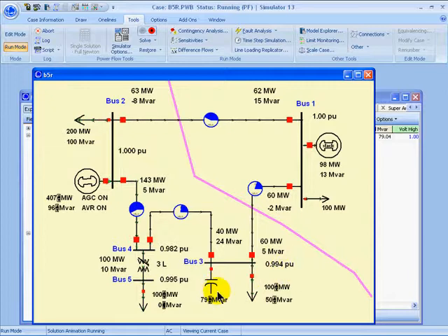So for example, I could reduce the megawatts and the voltage will creep up a little bit. I can get it to change even faster if I alter the reactive power at the bus. So if I start to decrease that, then the voltage will start to rise, and if it gets too high, we can see that the switched shunt reacts by taking one of the blocks out.